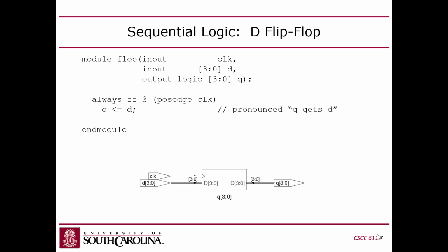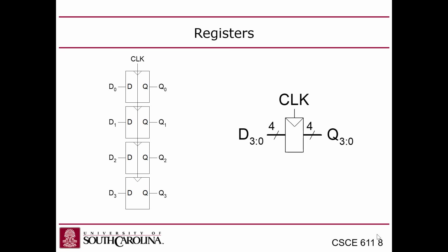So we'll have a stall signal that'll be set up in one of these always flip-flop blocks that will be asserted in the next cycle. You guys with me? It's a way to delay a cycle. It's a way to carry a signal forward from one cycle to a future cycle. You use this type of behavior.